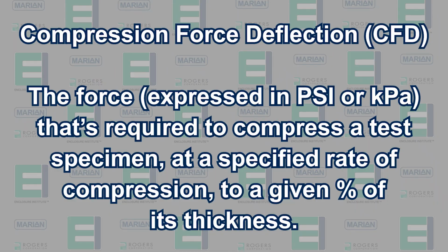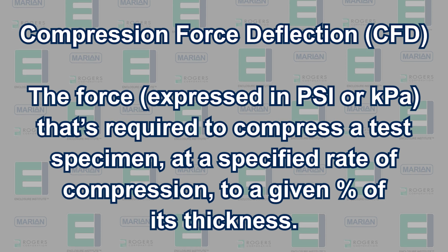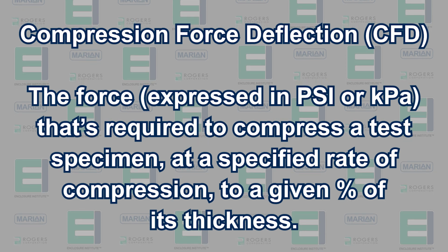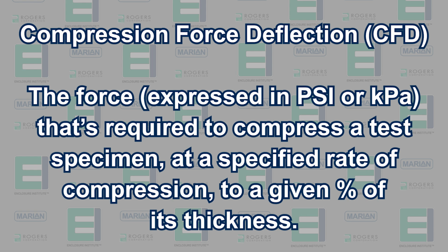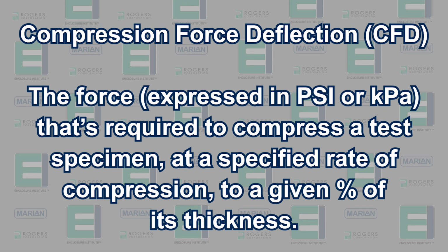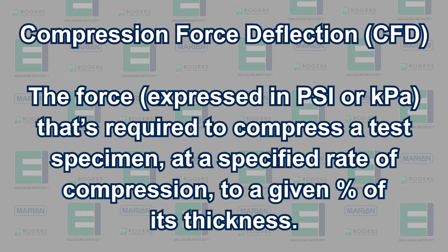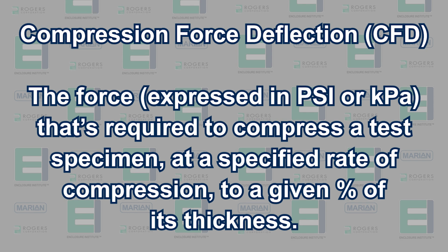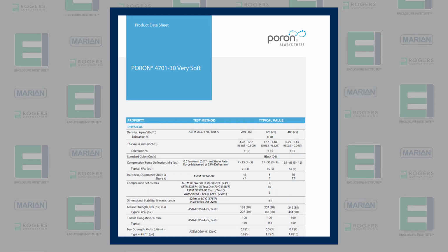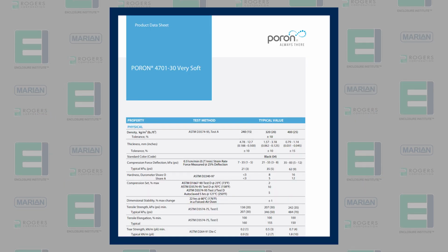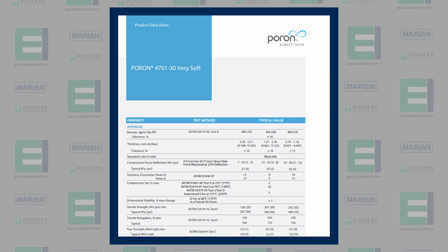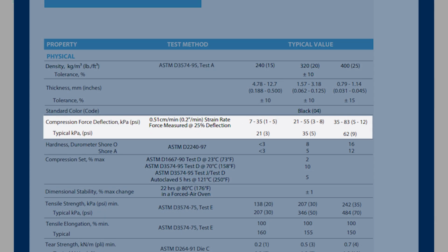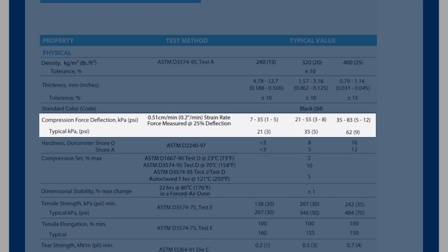Perhaps the most common cause of gasket failures over time is stress relaxation due to compression set. Before we dig into this topic, there are several concepts that we need to make clear. The first of these is compression force deflection, or CFD. This is the force expressed in PSI or kPa that's required to compress a test specimen at a specific rate of compression to a given percent of its thickness. There are various ASTM and other test methods that prescribe the details of these tests, but in simple terms, CFD is the measure of the foam's resistance to compression.